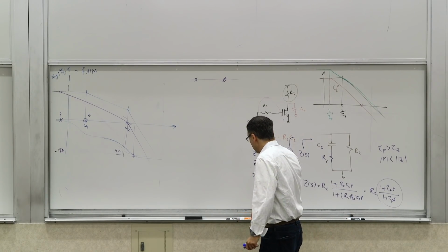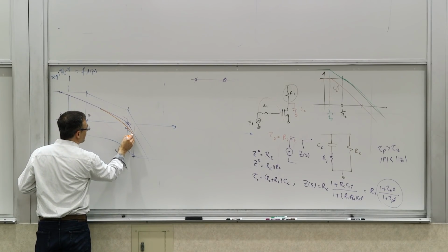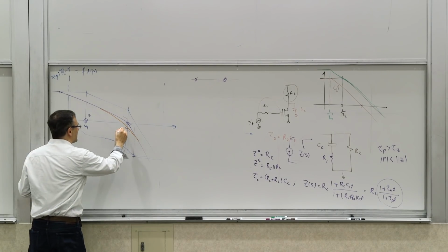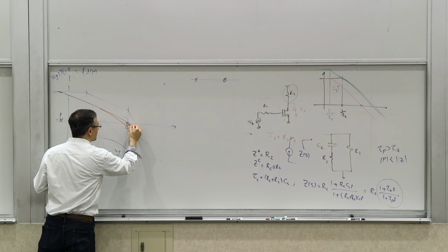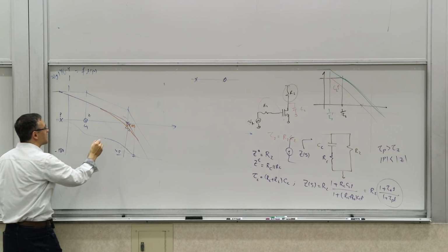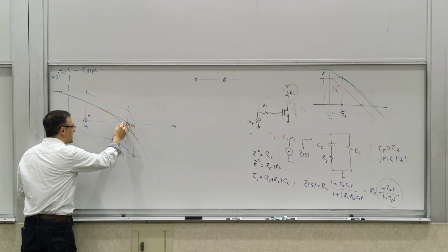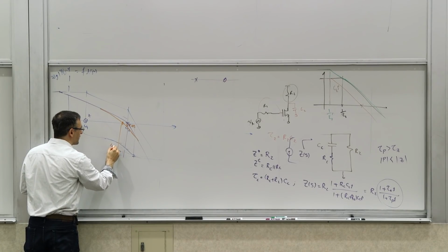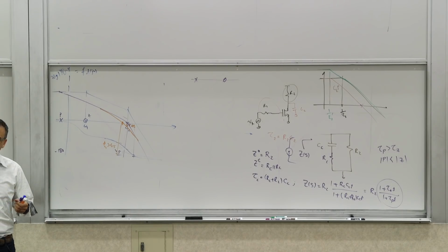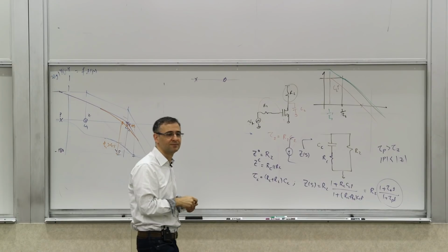Let me give you a few visual aids. This is the way the thing actually looks. This is 3 dB lower at this point. So your omega unity is really here, which means that you're getting more than 45 degrees, which is good because you design to start with 45 degrees, you get more, so you have a little bit of margin to play with.